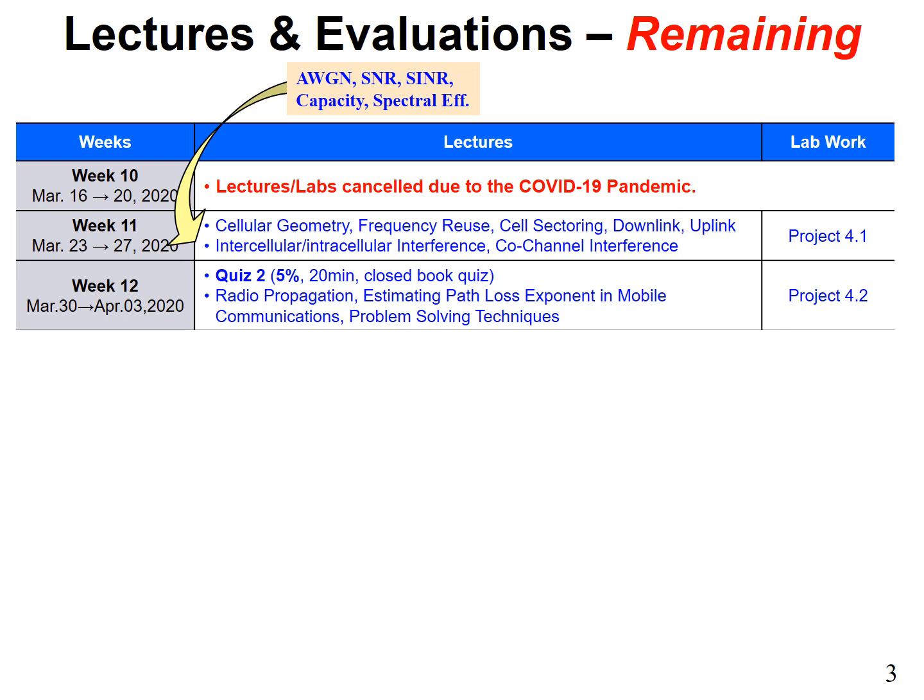This is a practical concept that you need to understand how it's performed, and then we'll get a sense of what path loss exponent means, and how it is different in different environments, and how you can actually measure it, right? How do you actually measure it? What do actual telecommunication engineers do to measure that?